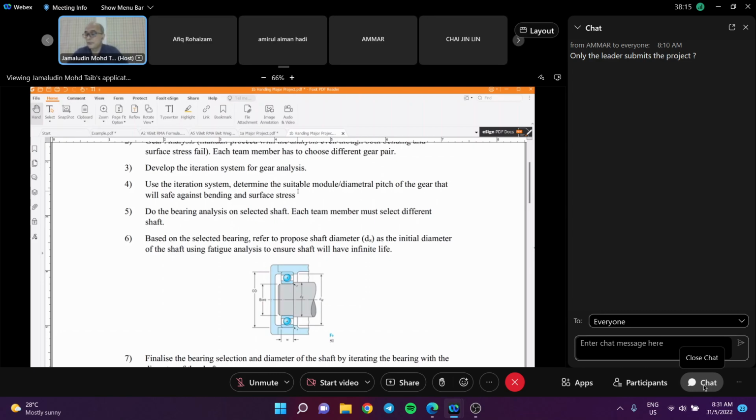Because imagine you have two feet to support. If it's a smaller one, it's very difficult to deflect, right? If you have a very long one, the shaft is going to be very easy to deflect. Okay, that's up to you. You have to do a bit of adjustment here. To me, I advise you to have a very short shaft, and between the bearings, let's say maybe 50 millimeter, don't try 150 and so on.